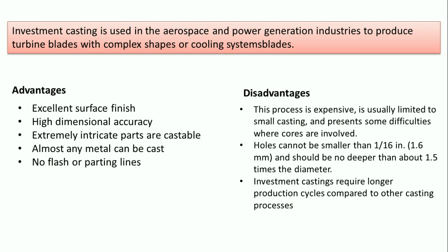Investment casting gives excellent surface finish. It also gives high dimensional accuracy. Extremely intricate parts can be prepared using this method. Almost any metal can be cast. No flash or parting lines are required for it.